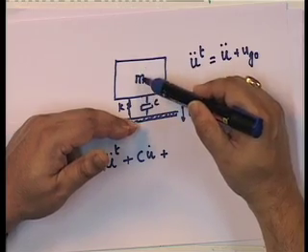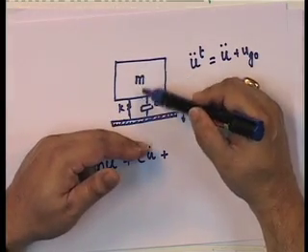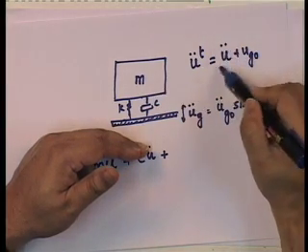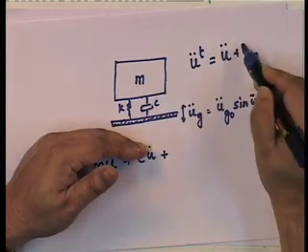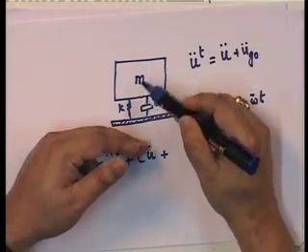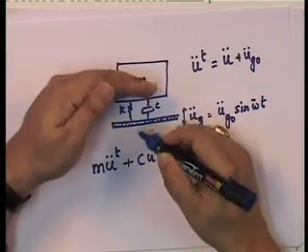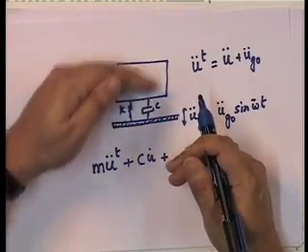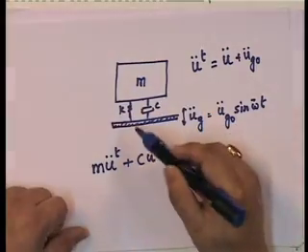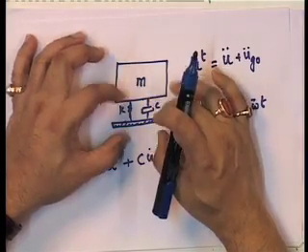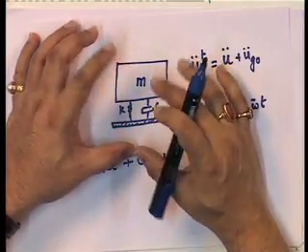Okay. But since this is moving also, the mass is being subjected to not only its relative acceleration, it is also being subjected to the acceleration of the base. So, the mass does not know that the base is shifting, the mass only sees itself moving. What happens to the spring and the dashpot is that they only see the relative movement.